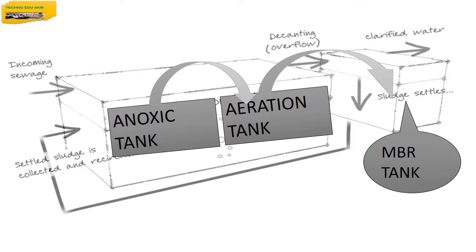Operation of the centrifuge is as follows. Switch on the centrifuge and wait till the centrifuge reaches full RPM. When the fresh water line has been running for 10 minutes, start feeding slurry by switching on the centrifuge feed pump and then immediately start the dosing of polyelectrolyte.